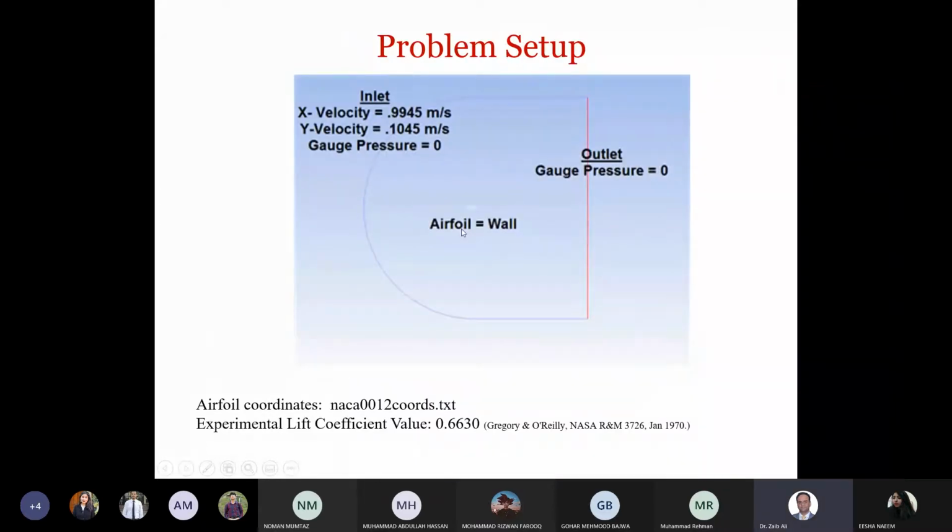Okay, so here's a look at our computational domain setup. Here, this small white line is the aerofoil basically. And what we want to do is construct our computational domain or a far field away from the aerofoil. The aerofoil has a chord of 1 meter. This blue line is the inlet, and the air is coming at an angle of attack of 6 degrees.